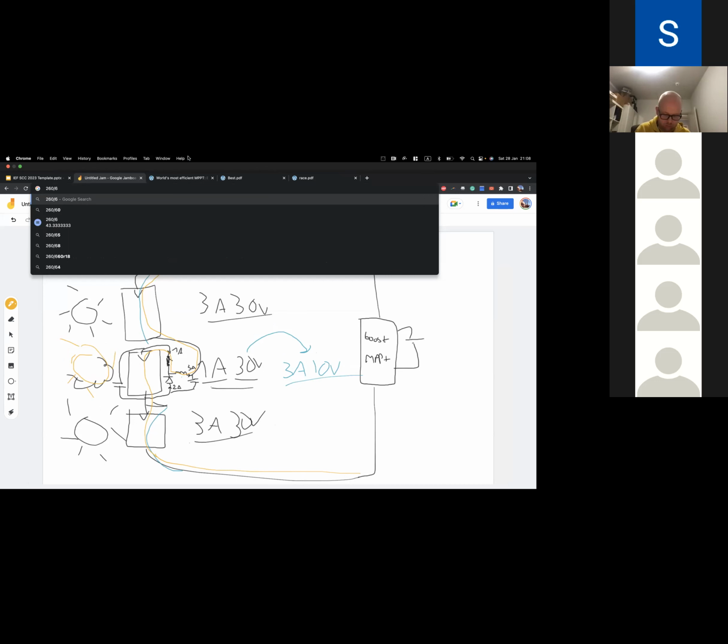Well, that would be relatively easy to implement. You have these boards that can measure 16 voltages. But the important thing is once you have the IV curves of these groups of cells, you have to know how to interpret it. Yeah, you need to know what you're doing. It's interpreting the curve that then tells you what you need to do, and it may mean you have to replace the module, obviously.